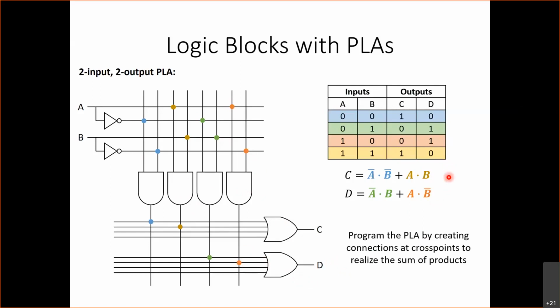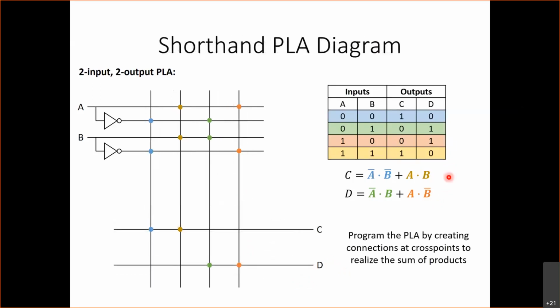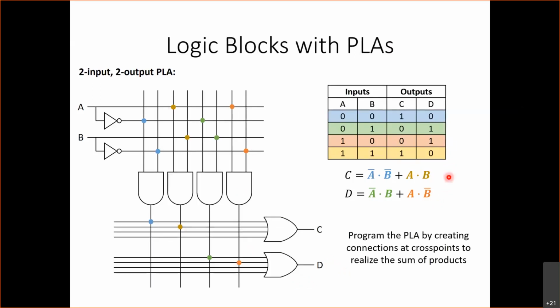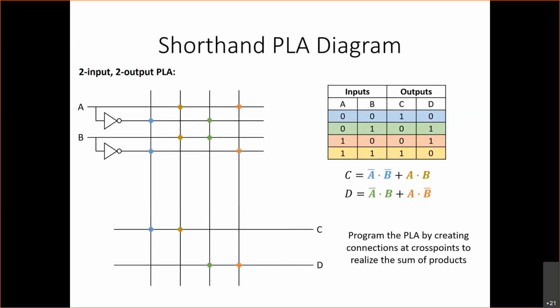Okay, if there are no questions, I'll move on. So let's look at a shorthand way of drawing PLA diagrams. Rather than drawing all these connections, all these lines, and all these AND gates and OR gates, a shorthand way of representing a PLA diagram is like this.